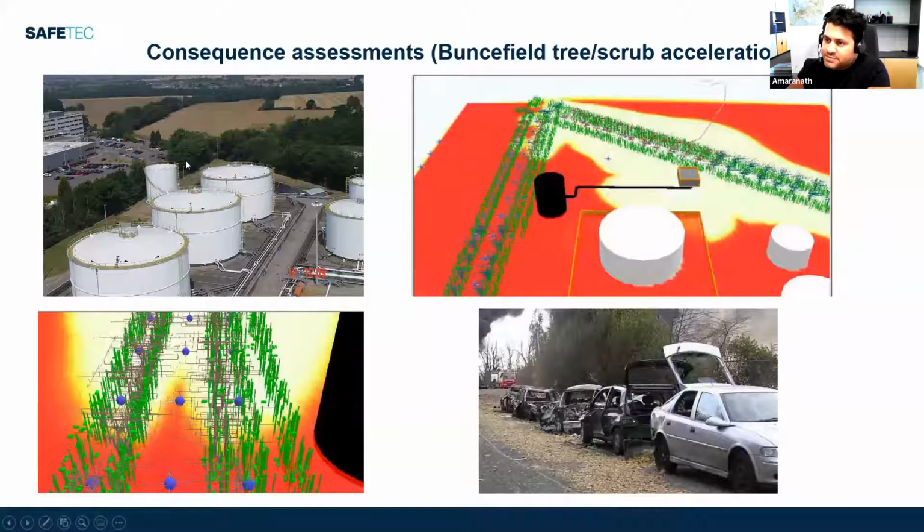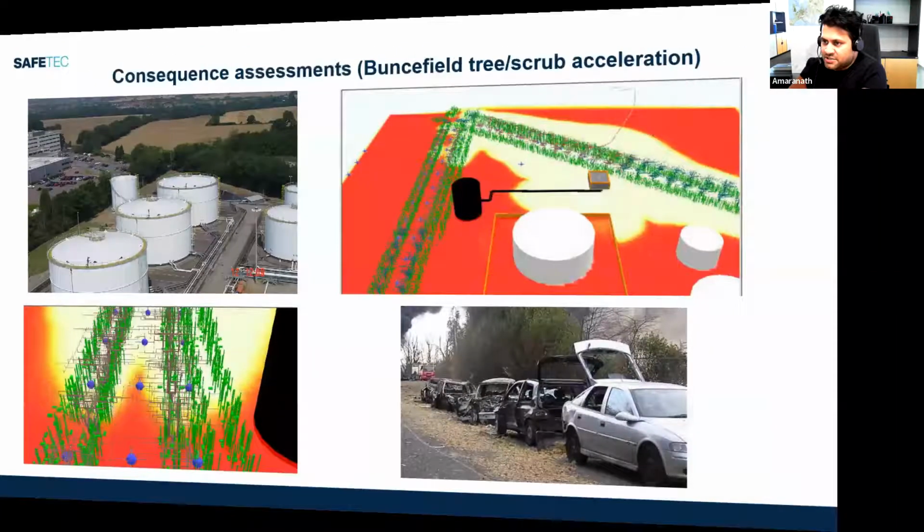So in this case, you have experienced a detonation. So you have explosion waves which are traveling quite fast, and to model the consequences that they have observed on the vehicles and surrounding area, you have to include, for example, even the minor objects like trees and the objects that you have with the pipelines and other constructions in the facility. So consequence modeling is very important, very important when it comes to offshore risk assessments.